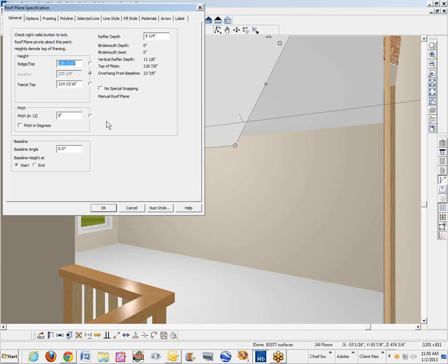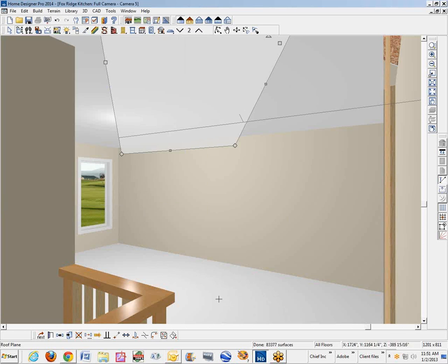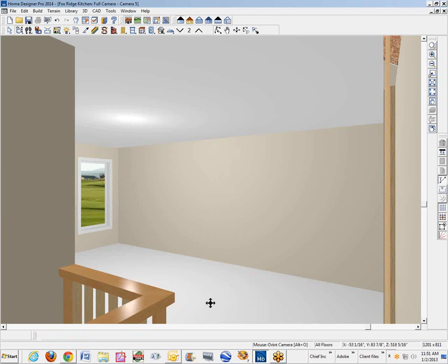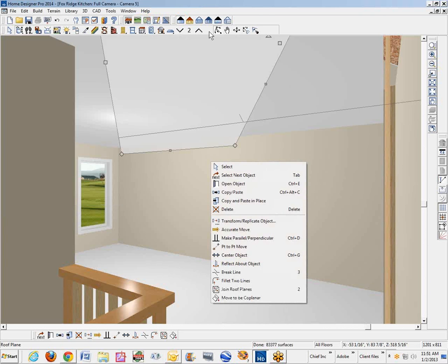It looks okay at a glance, but it's not okay when you look at where the baselines are and so forth. On the one hand, I said you did a good job, and on the other hand, it's terrible in terms of technical correctness. I think the roof planes as a group are what's causing this, because this is the evidence. I click on down here, and I get a roof plane. That's totally goofy.